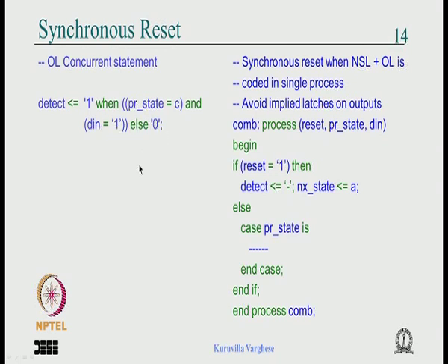So you can write like that, and here to write with select is difficult because you have 2 inputs. If you are adamant, then you can do that. What you can do is group present state and the D in together into a temporary signal, then you say with that signal select and put this value and so on, okay.